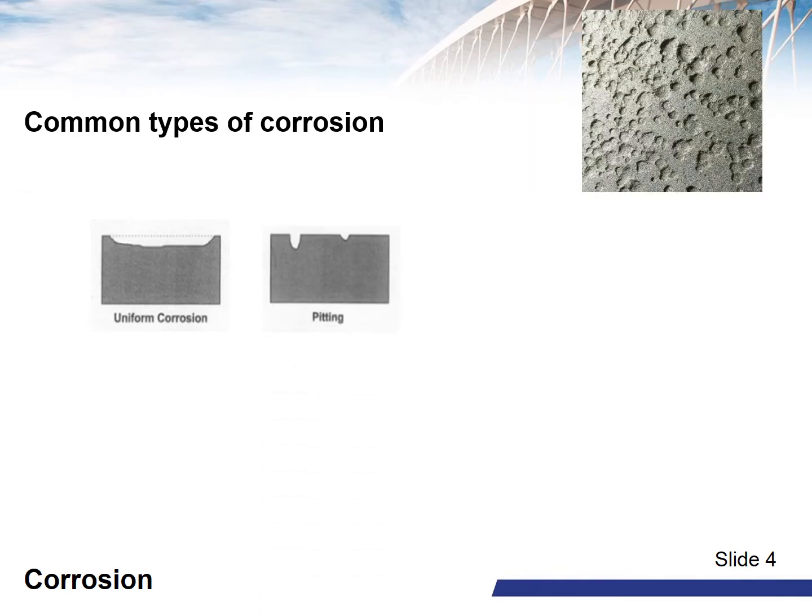Pitting corrosion. This is one of the most aggressive forms of corrosion, and pitting can be hard to predict, detect or characterize. This localized type of corrosion happens when a local anodic or cathodic point forms a corrosion cell with the surrounding surface. This pitting can create a hole or cavity which typically penetrates the material in a vertical direction down from the surface. Pitting corrosion can be caused by damage or a break in the oxide film or protective coating, and can also be caused through non-uniformities in the structure of the metal. This dangerous form of corrosion can cause a structure to fail despite a relatively low loss of metal.